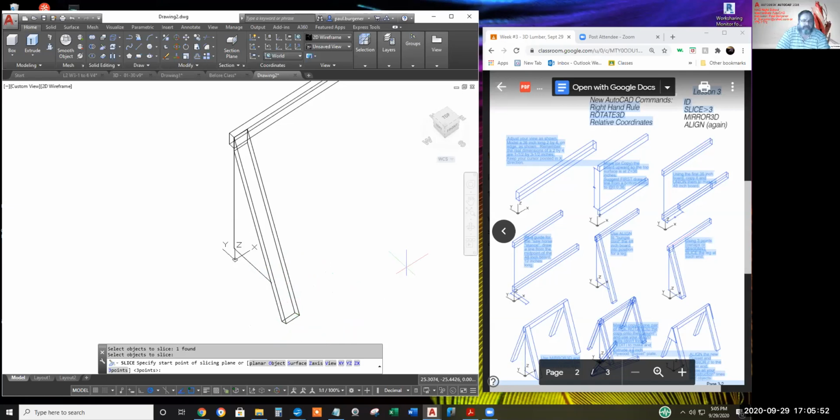Again, I always use a 3-point, and you just pick points out here in random space, being careful you don't follow any of the polar tracking lines, especially the Z direction polar tracking line. But 3 points out here in space will define 3 points on the Z = 0 or the XY plane. Let's click on XY, and I believe any point along this little chalk line we drew here will be good.